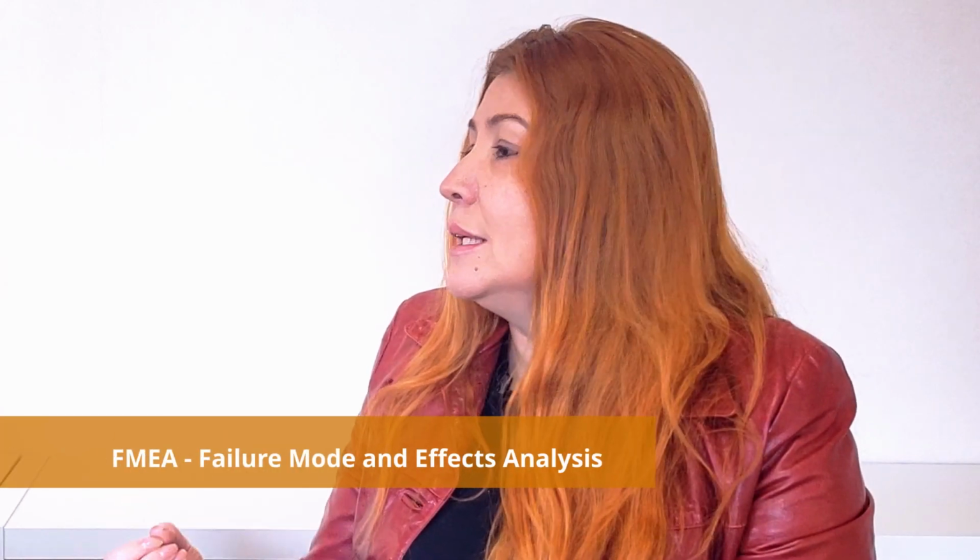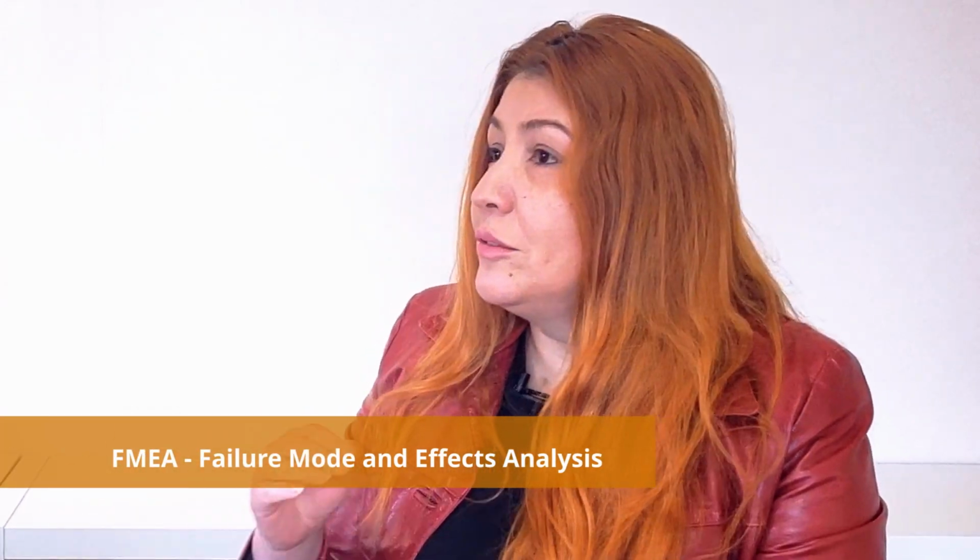Another analysis that you can do is the bottom up. The bottom up, you start in the lowest level that you know. So depending on the phase of the project, it can be a subsystem, but if you are more advanced, it can be in the item level. And this is a very important tool to evaluate single failures. The most common method is the FMEA, that's failure mode and effect analysis. So you evaluate each failure mode of an item and verify the consequence. So then you can check if one single item can result in a failure condition. So then you can check the single failure.